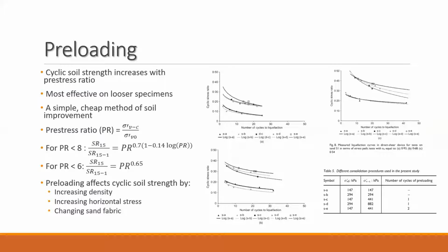The figures on the screen clearly depict this relationship, as the samples that received pre-stressing prior to loading all displayed a larger resistance to cyclic shear stress, whilst also showing that overall the samples with the higher void content had less of a decrease in shear strength from initial to failure conditions, whilst denser samples had an overall increase in cyclic shear strength.